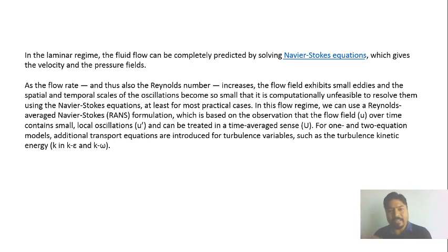All our turbulent models are developed on the basis of the Reynolds averaged Navier-Stokes equation, which is a time average equation, and based on time we consider the variation or fluctuation in the velocity in that fluid flow region. By using this we can solve the turbulence in any flow field.